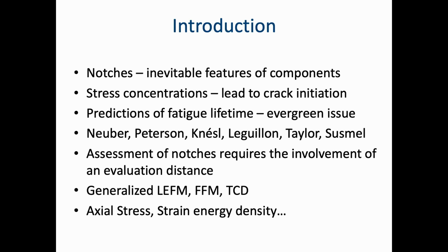These approaches are called generalized linear elastic fracture mechanics, finite fracture mechanics, theory of critical distances, etc. And all these approaches somehow require the involvement of an evaluation distance. On this distance, we usually evaluate axial stresses, strain energy density, plastic zone size, and so on.